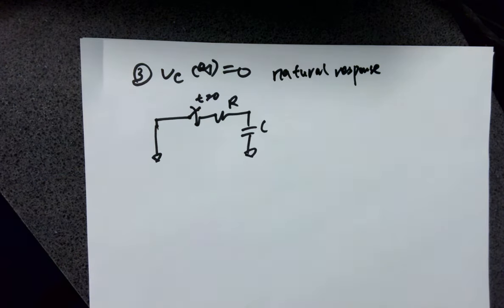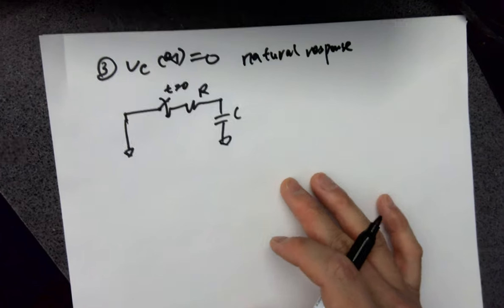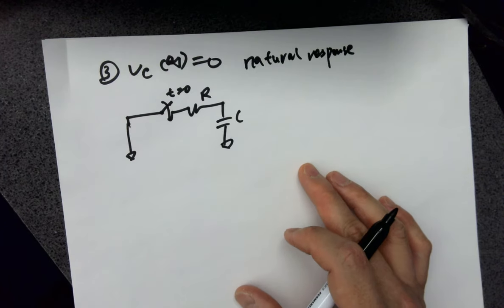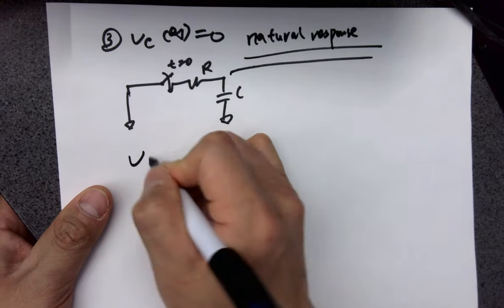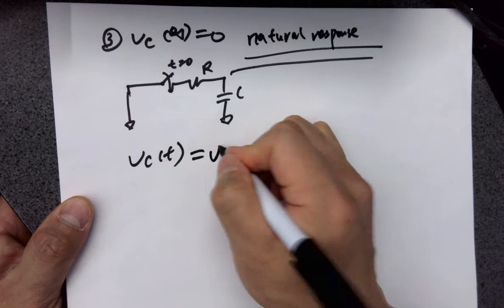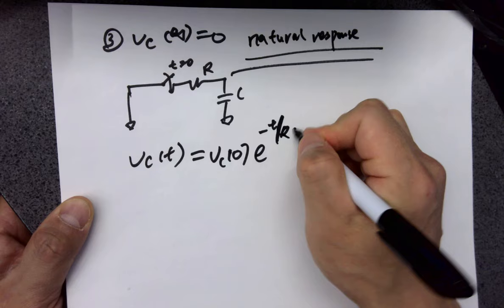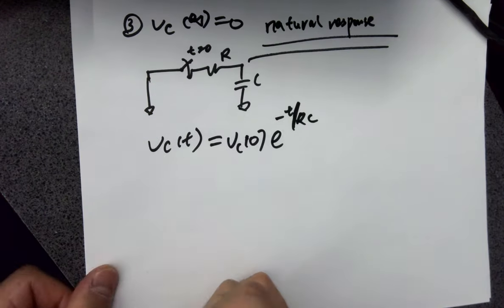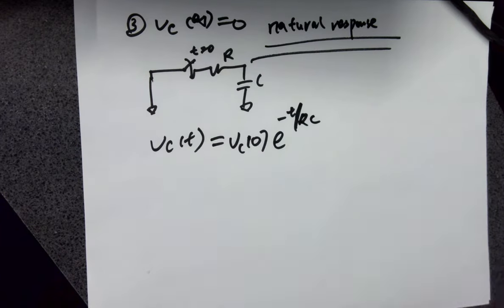All right. So this simple example covers about 2 weeks of RC circuit classes in Circuit 1. It summarized everything. That's everything you need to know. And a lot of times these kinds of things appear in interview questions. Could be one of the interview questions. So natural response, VCT equals what? It's simply just discharging from the cap, right? So what is VCT? It's just the initial voltage, discharged using this attenuation factor here. Very simple, but this is not the case for our digital circuits. We only want to look at the second one, which is this one.